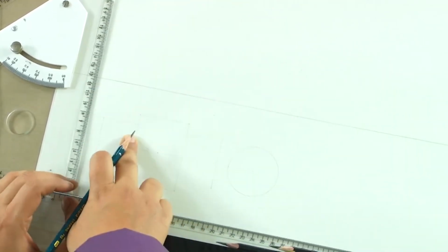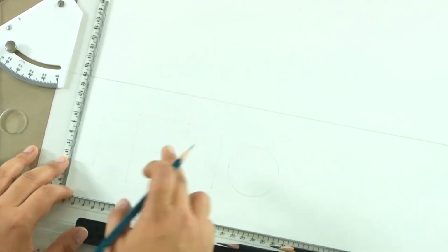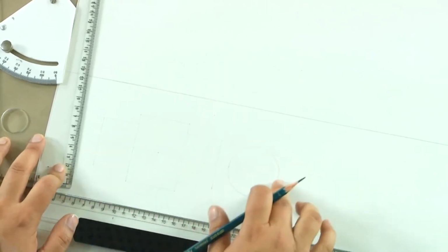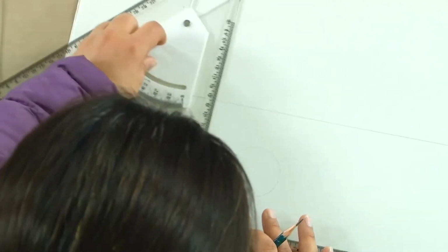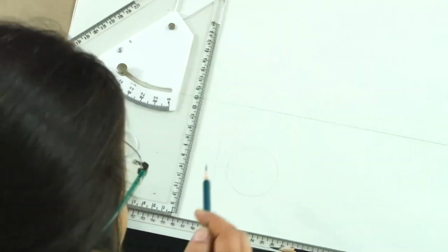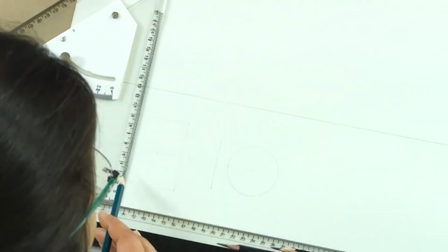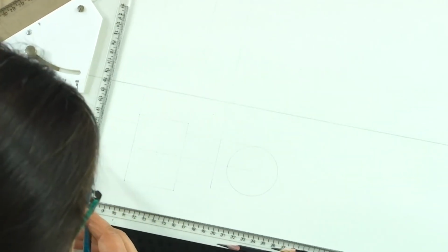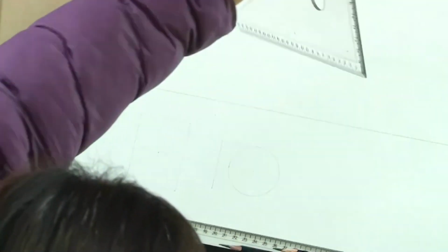So, this is what we are going to see, while this other cylinder, a circular cylinder which is intersecting it, has its axis parallel to both HP and VP. So, we will not be able to see the base of this cylinder. Now, if we see it in the front, what do we see? We will be seeing the cylinder where the axis is parallel. So, we will still be seeing a rectangular shape for the cylinder, and for the prism we will be seeing the front face of the prism which is parallel to VP.